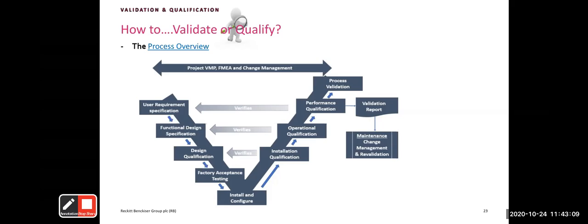So you look at the list, you look at the documentation that came with it, and you look at the spacing of where the equipment was installed. You now look at things like the mechanical requirements, the electrical requirements. You want to be sure that they're all meeting what you specified in your user requirements. You look at the safety requirements you asked for. Do they have audiovisual alarms? All these are things you look out for in an installation qualification exercise.